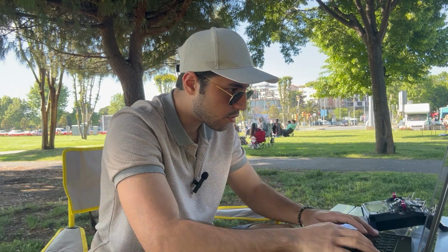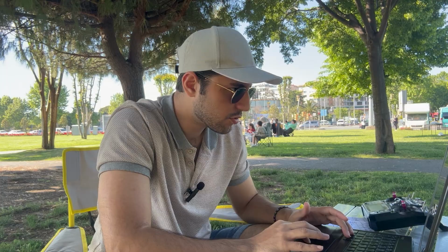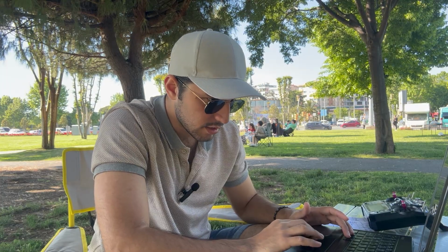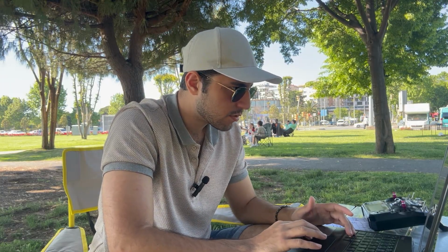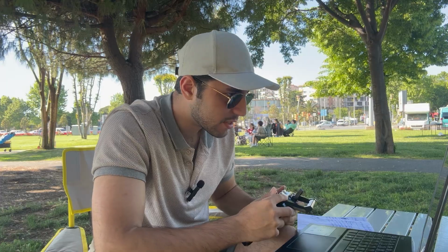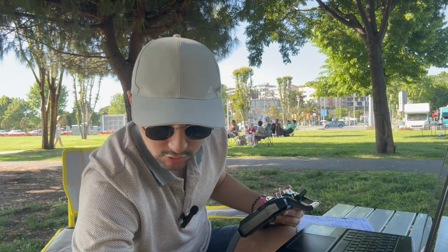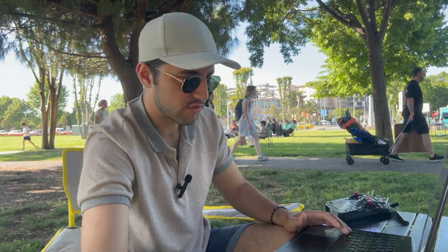So first I open my ground control station. I'm going to show you my setup afterwards. First I'm going to show you the HITL testing. Now currently, as you see, the airframe is chosen as HITL configuration. So let's see what the errors are. One of them is probably happening because the GPS is going to get a fix in a few seconds. It would be connected.